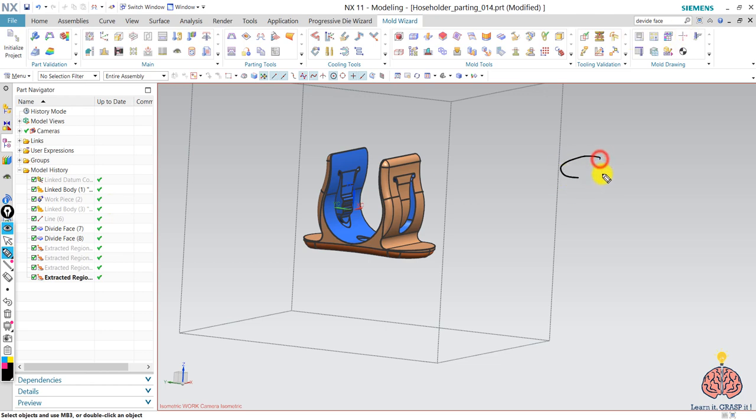So let's make a cylindrical part with a cylindrical hole in it. All right. And we want to make this part with injection molding. So if you can imagine, the parting surface will be right here.